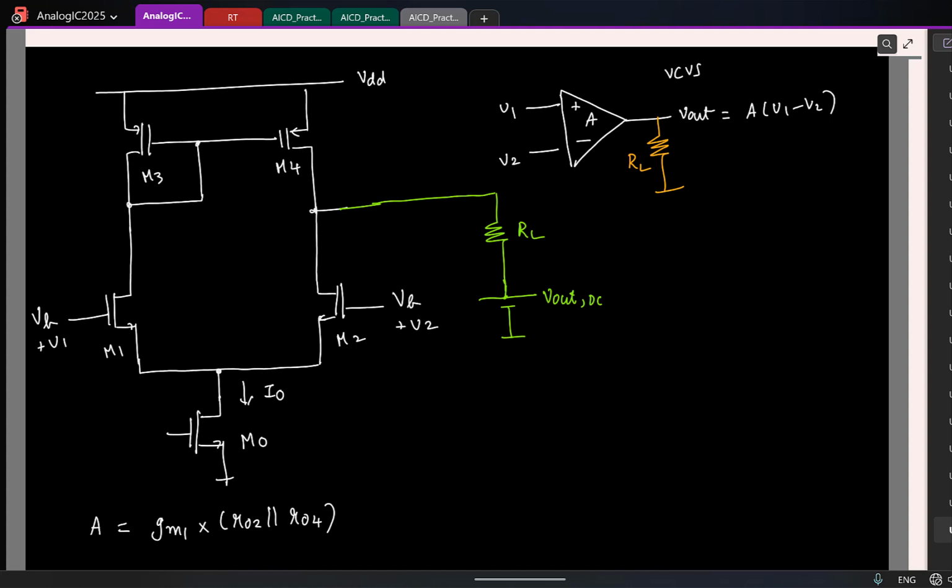So now of course tell me, I mean for small signals this is anyway small signal ground. So now with the addition of load RL, how will the gain change here? Or will it not change? What will come in parallel with what? The output resistance will come in parallel with, it's going to come in parallel with your existing output resistance like this. Is that okay? So which means now with the load resistor, do you think my output voltage will change or will it not change?